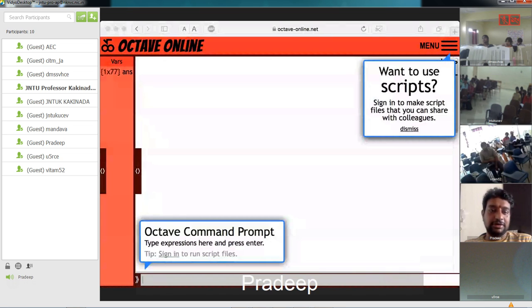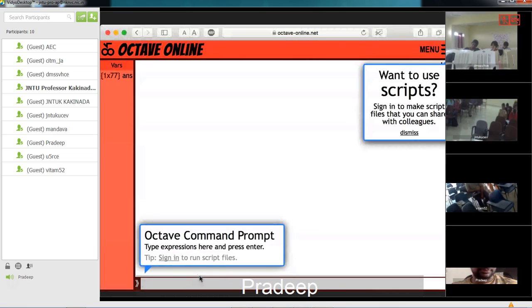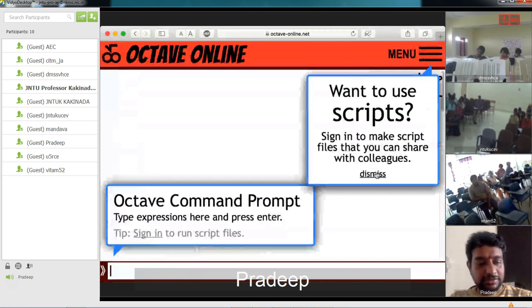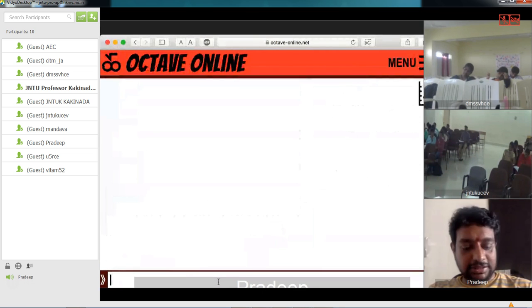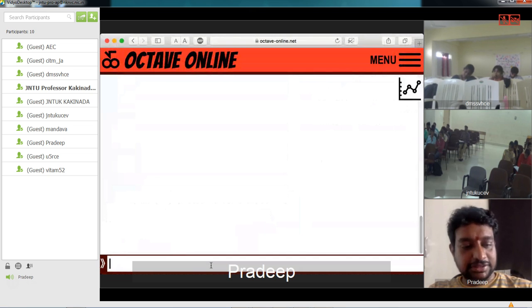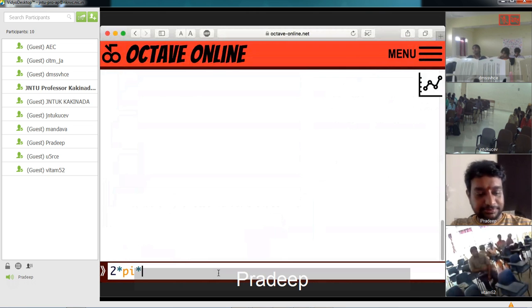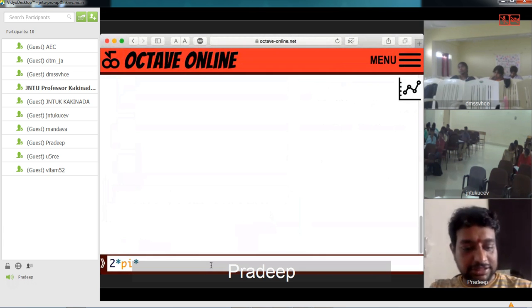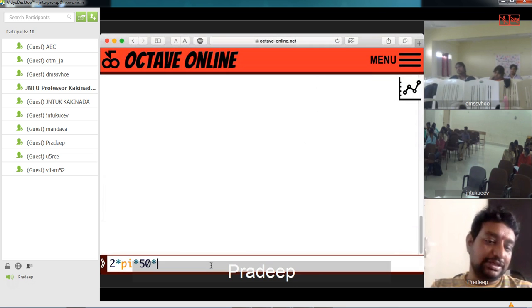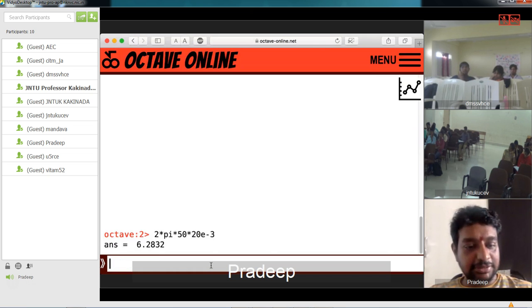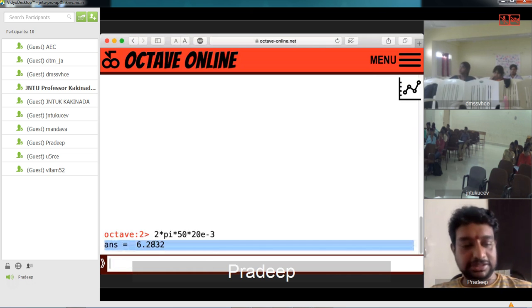You can just go to octaveonline.net. I'll be entering my commands at the bottom. I'll write 2 into pi into frequency 50 into inductance 20 e to the power of minus 3. This gives me the value of the inductive reactance. On the screen you can see 6.2832.